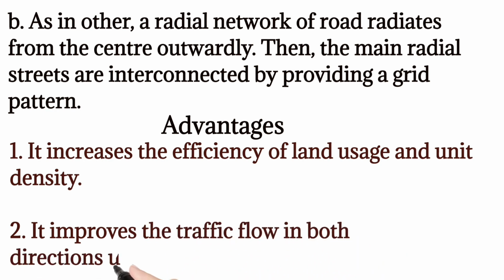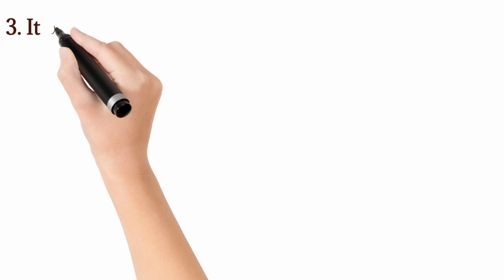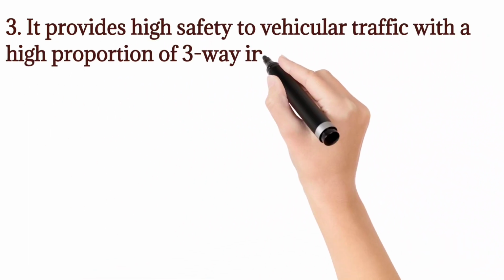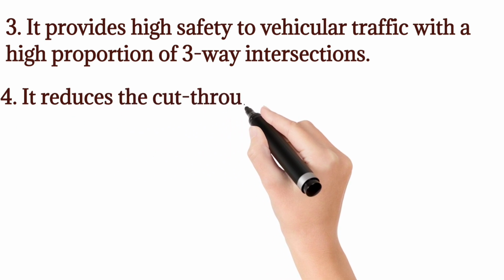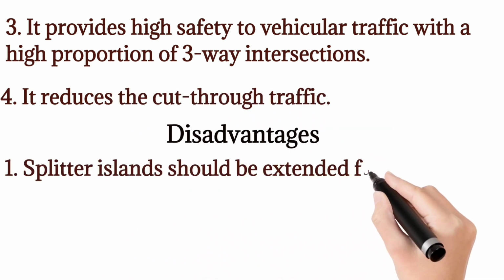Advantages are: it increases the efficiency of land use and unit density. It improves the traffic flow in both directions utilizing cellular structure. It provides high safety to vehicular traffic with a high proportion of three-way interconnections. It reduces the cut-through traffic.